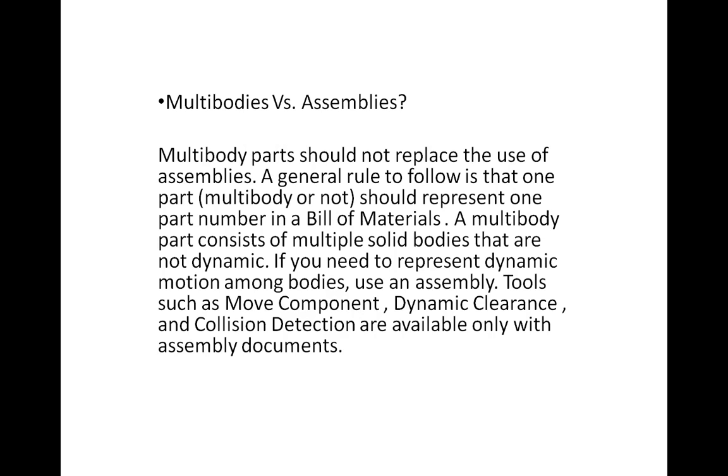Now, this is straight from the SOLIDWORKS help. And as I put together this presentation, I really think that this general statement is getting very, very blurry as we move forward with the SOLIDWORKS product. Let me just read this for you. Multibody parts should not replace the use of assemblies. The general rule to follow is that one multibody part or not should represent one part number in the bill